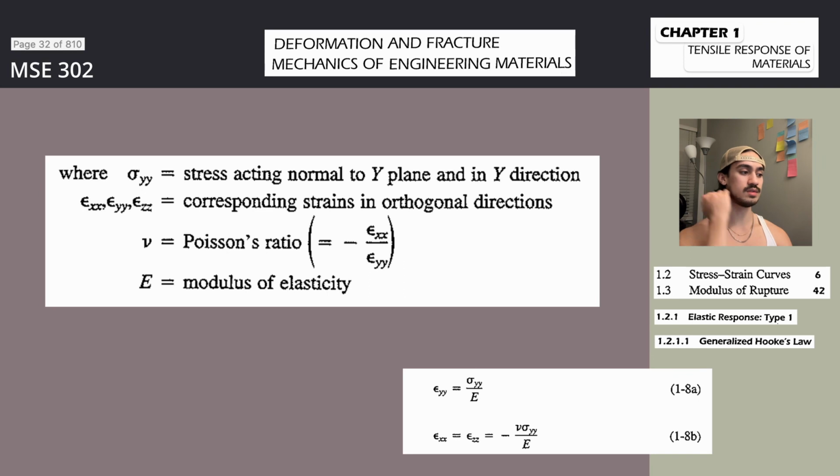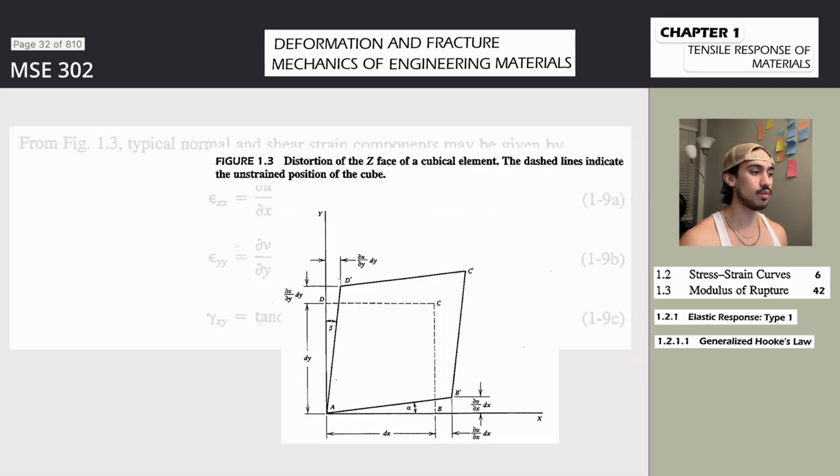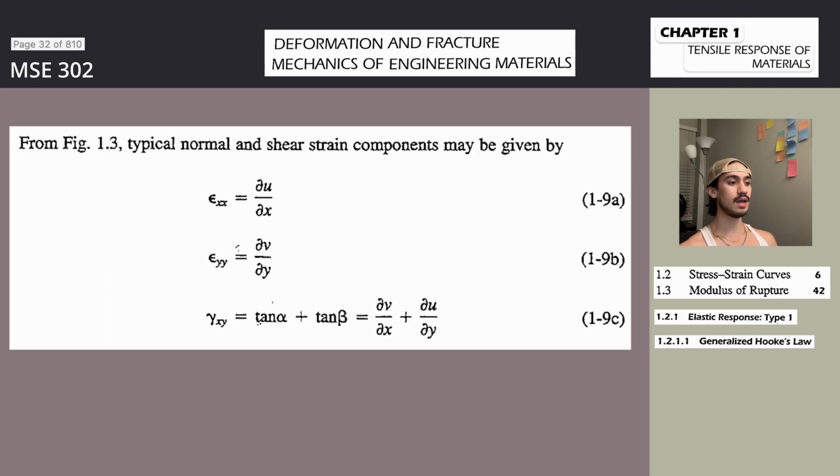Equation 1-20, where sigma is the true stress, epsilon is the true plastic strain, n is the strain hardening coefficient, and K is the material constant, defined as the true stress at a true strain of 1. However, Bulfinger proposed a similar parabolic relationship between stress and strain almost 200 years earlier.